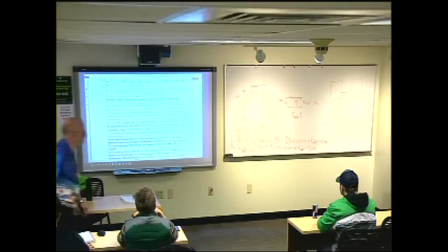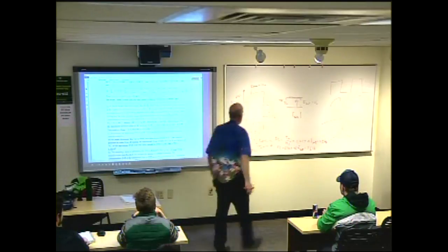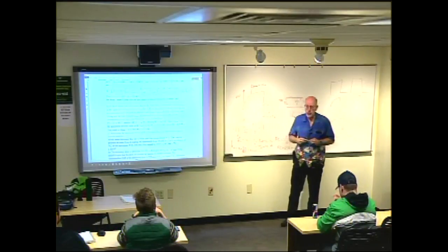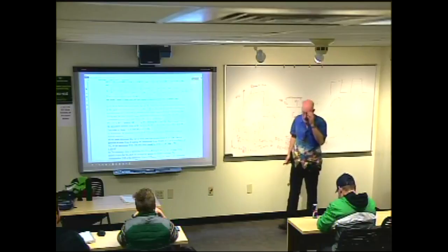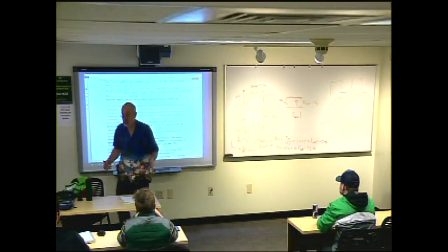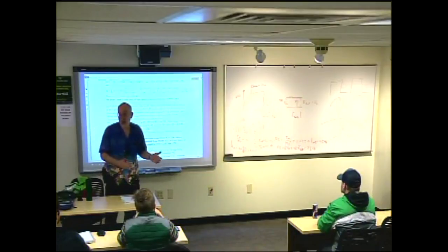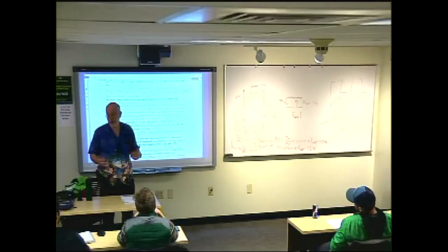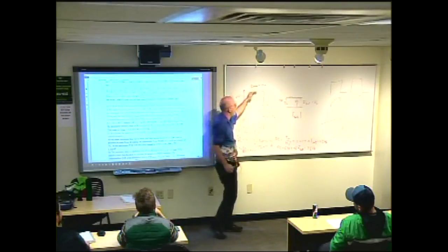Well, these times are not the duration of something. If you remember, this point out here is like at 120 seconds, right? They're not the duration, they're the characteristic. It's kind of like if I said I wanted a 100 hertz signal and a 20 hertz signal to go through a filter, I wouldn't say, okay, I need a 120 hertz filter by adding them together. And it's kind of the same notion here. You wouldn't add the taus together for them to go through. Only one of the taus at a time is in play.